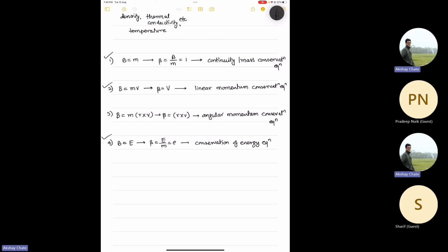Therefore, in thermodynamics, all the steam tables that you use have enthalpy in kilojoule per kg, right? Internal energy is in kilojoule per kg. The specific volume is in meter cube per kg. All of them are intensive properties, and since they are intensive properties, everybody can use them, and whatever mass of the system they have, they can just multiply with that mass, and they will get the extensive property. So that is the significance of extensive and intensive.